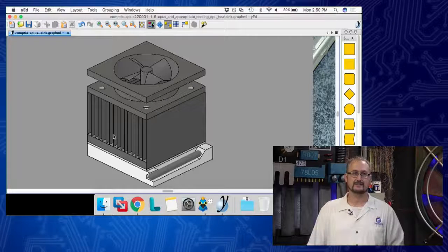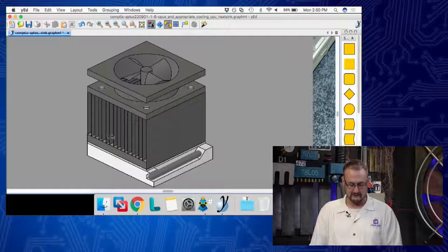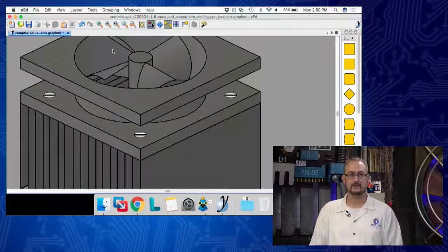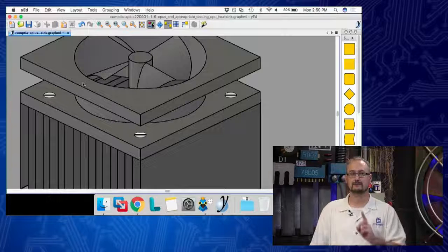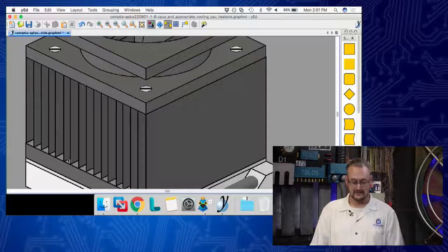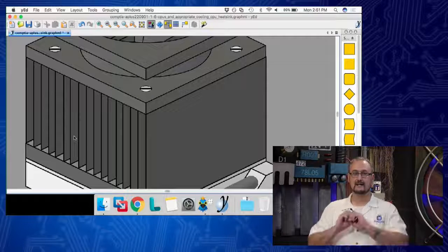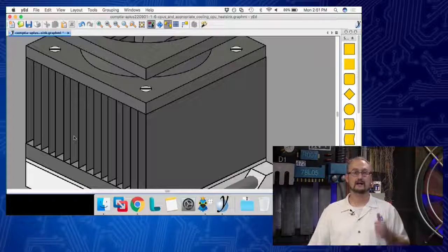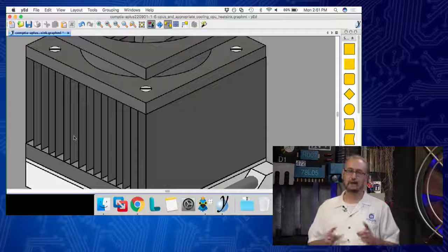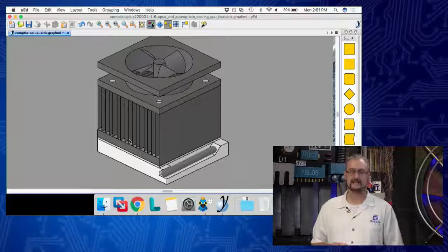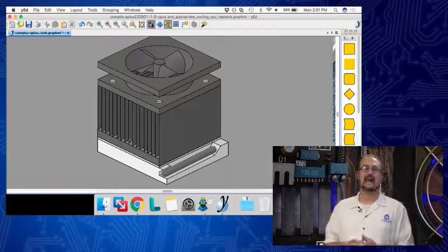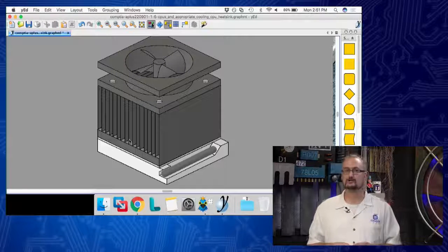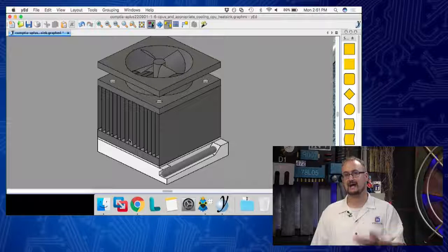Now, the other thing that it does is it actually draws heat into these valleys right here, between the fins. And what you'll see is that we have something on top of it known as the CPU fan. The CPU fan is responsible for taking that air that's essentially heated up within those valleys and dissipating it, blowing it out of the heat sink itself so that it helps to assist the cooling. Now, more specifically, when you have a fan like this with a heat sink, that is what is known as an active cooling system.